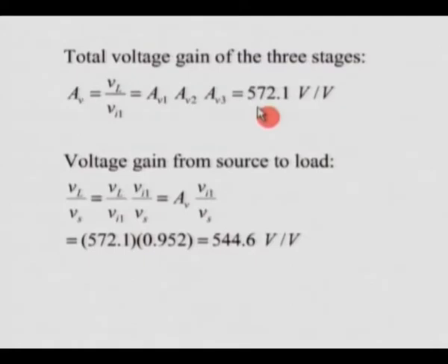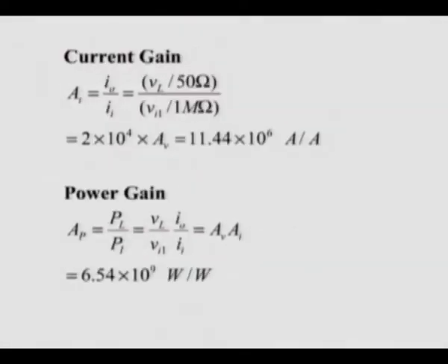So, if you see that, without that fraction, if the input resistance were infinite, then AV and the overall voltage gain would have been the same, but here the input resistance being only 1 mega ohm, we see it drops. So, the higher the input resistance for the first stage, the closer these two numbers would be. So, this is a very good example to illustrate what we are talking about.